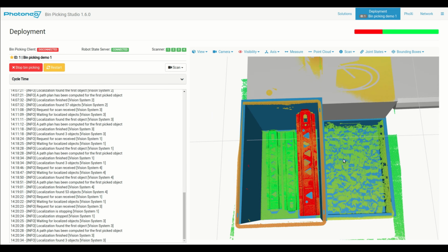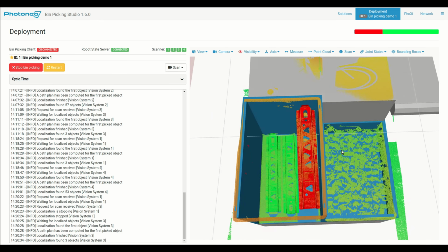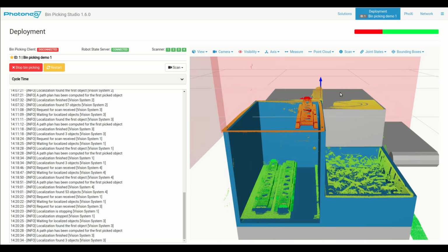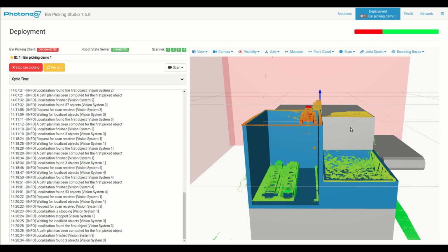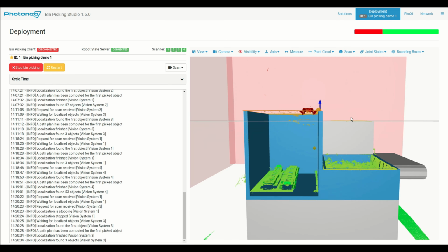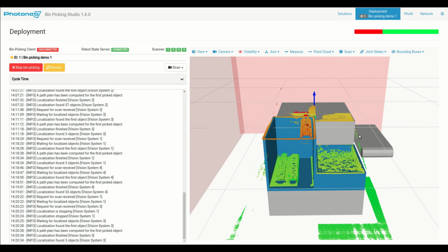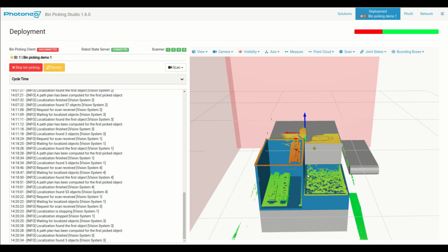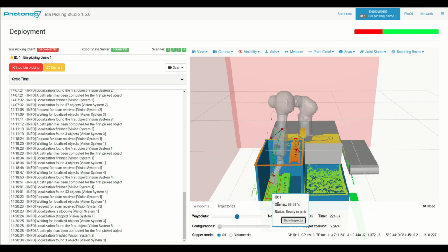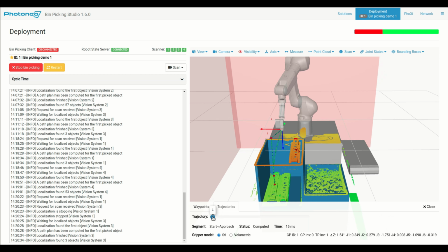Suppose we have two types of objects we want to pick, placed in different bins. One object is considerably larger in comparison to the bin size. The bin is also deep, which makes the picking of such an object from the bottom of the bin a bit complicated, as there is not much room for maneuvering. After grasping the object, we will want to move vertically upwards in a linear path until the object is outside of the bin.